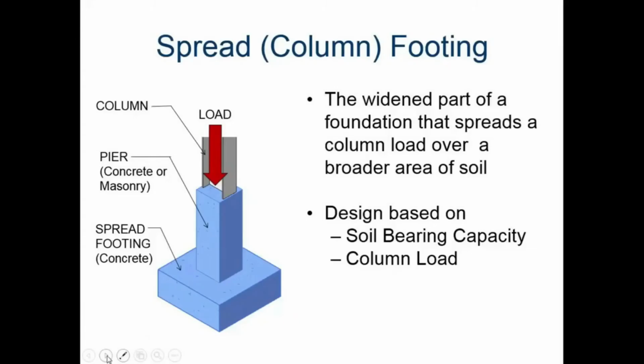Spread footings. Spread footings are the simplest kind. They are used on bearing surfaces of rock or of soil that is packed solidly like hard clay. It is a pad which may be long and rather narrow to go under a wall, or it may be square or rectangular where it is to go under a pier or post.